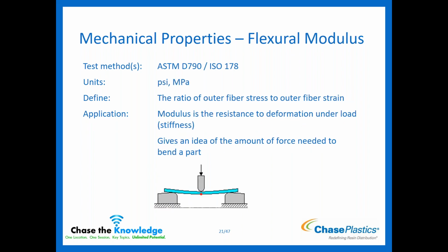So flex modulus, so similar concept to your tensile modulus, it's going to be the resistance to deforming. But in this case, and for flexural stuff, it's going to be bending. So I'm pushing down in this direction. So instead of pulling it apart like you do for tension, flex, I'm pushing down right in the middle of a beam. And so that's going to be what your flex mod is.